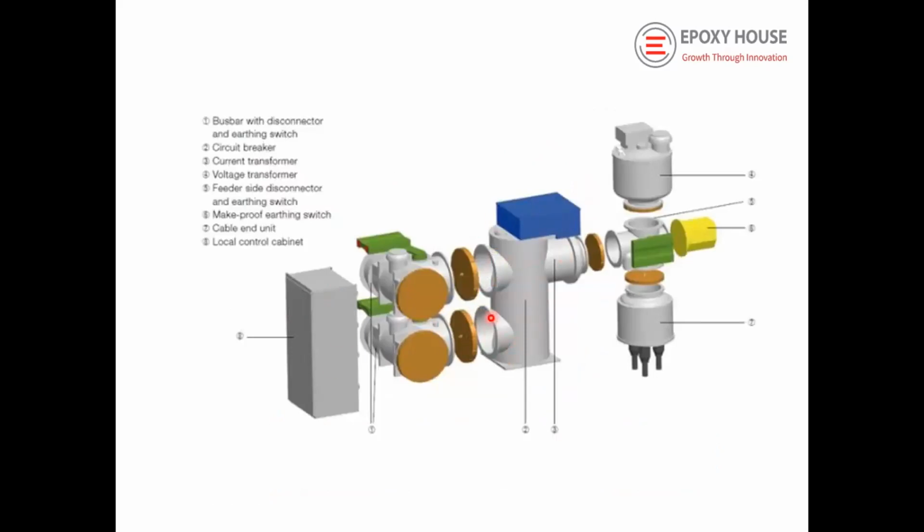This is again the circuit breaker. These spacers act like separators of the gas movement. The enclosure is supported by the spacers on both sides. So here the circuit breaker is enclosed with three spacers, and this divides a gas compartment.